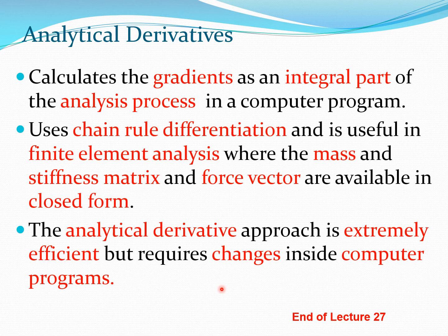Maybe you are interested in a robust or reliability design problem where you need to make an enormous number of calls to the function because your optimization loop is outside a Monte Carlo loop for the particular problem. This can happen because some of the objective functions which you are using in robust and reliability based design are actually statistical in nature.